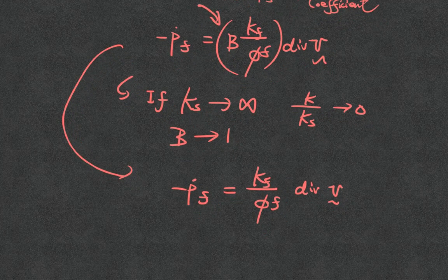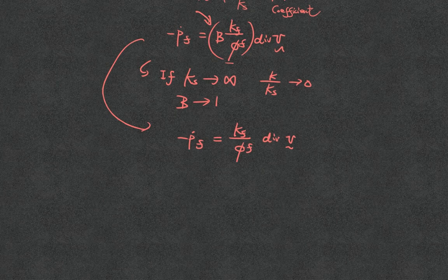So strictly speaking, this is not a linear function because the porosity and rho f actually also depend on the P itself, right? Does that make sense? But if you're assuming that the void ratio is not changing that much, you can assume it's constant. But that won't work for modeling something like a pore collapse or a sudden big change. So that nonlinearity has to be taken into account.